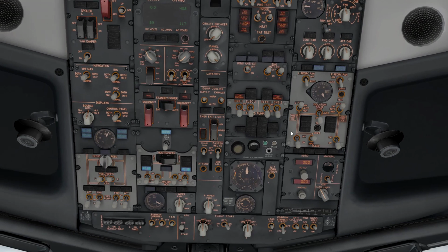Scrolling down, we've got sort of a silvery section that's substantially lighter in this 4th panel row, and that is going to be all of our high pressure bleeds from the engines and the APU for starting, as well as running the cooling packs, the AC and heat. So just take note of where that is, because we're going to be looking up here a lot through the